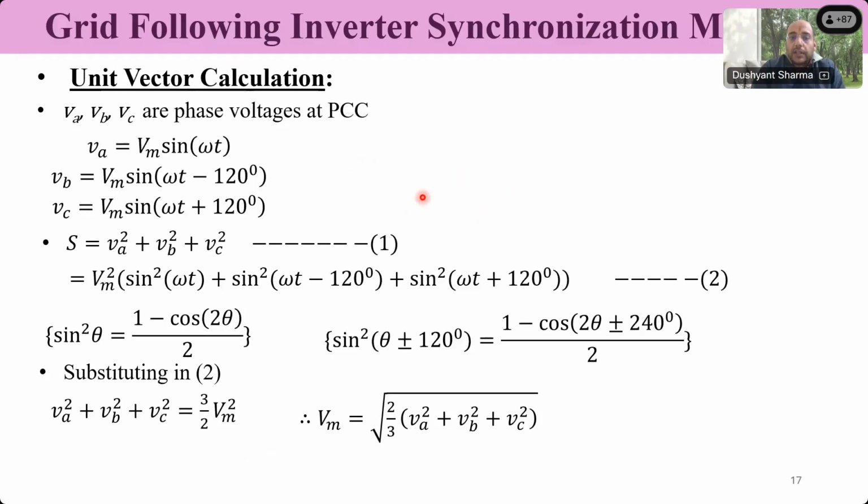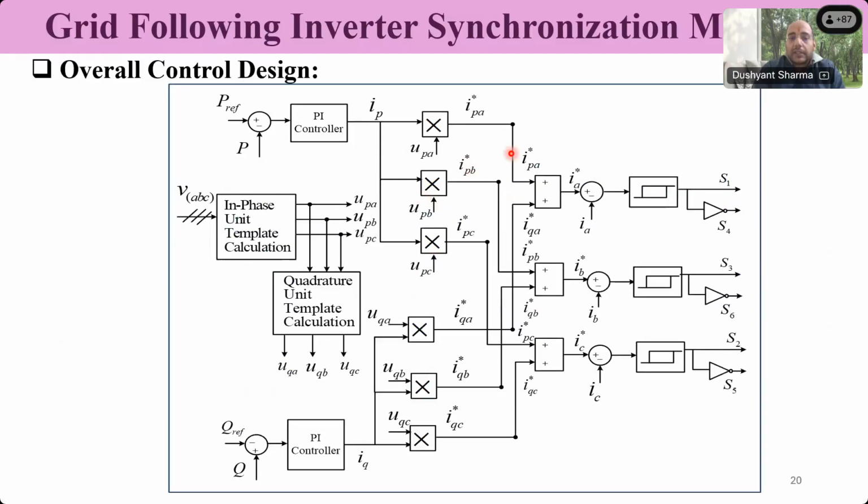On the contrary, in the present case, our currents are time varying sinusoidal currents: IA reference, IB reference, IC reference. If we compare with the actual IA, IB, IC, we cannot directly use PI controllers. Why? Because, as I told, PI controllers are suitable for DC quantities. Designing a PI controller becomes difficult for time varying quantities. Therefore, we have to use a separate control.